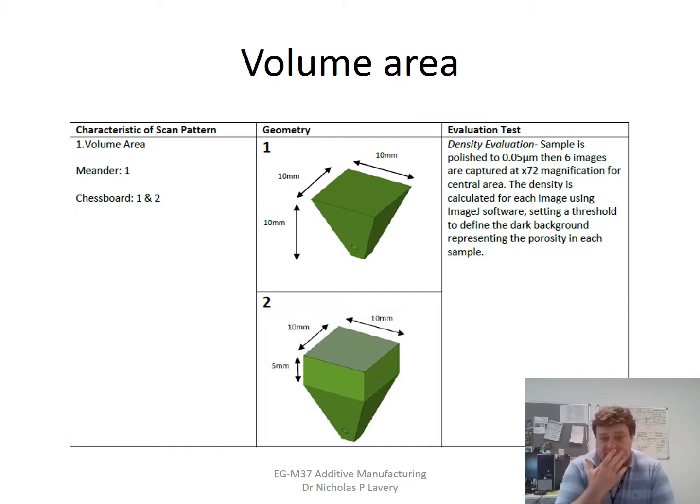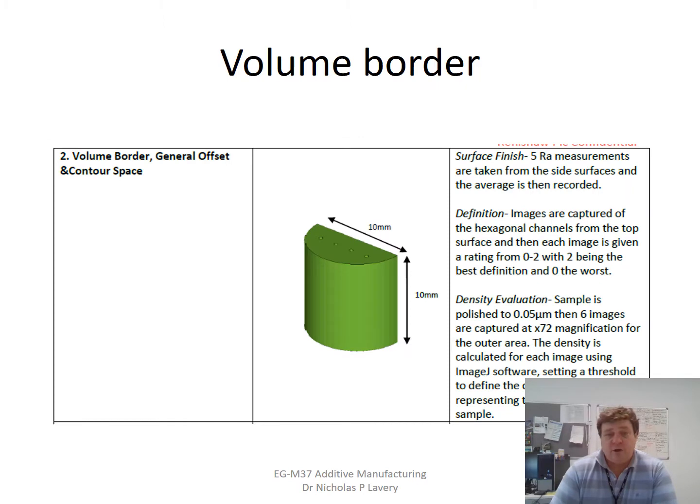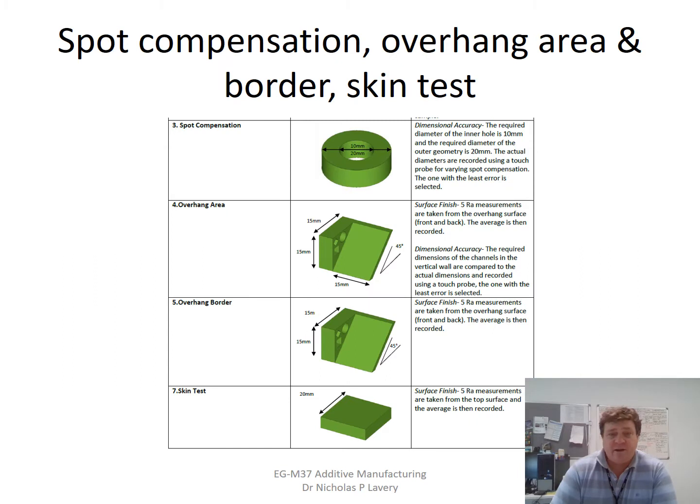And we have a series of very standard tests that we have test plates, and we'll put them on. We will look for material properties like density through parts which look similar to this. We'll look for the surface finish and density, with parts like this. We'll have some holes in it to see how well the holes have been made. We'll look to see for the dimensional accuracy.